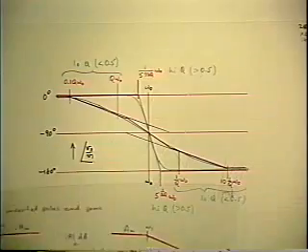So there's a summary of the salient features of the two cases for quadratic solutions, which applies not only to the RLC network, but of course to anything else that comes up with the same formula, which, as we'll see later, includes the problem of the crossover of the loop gain in feedback systems, even though there's no inductance in sight. One further little extension we can talk about right now.